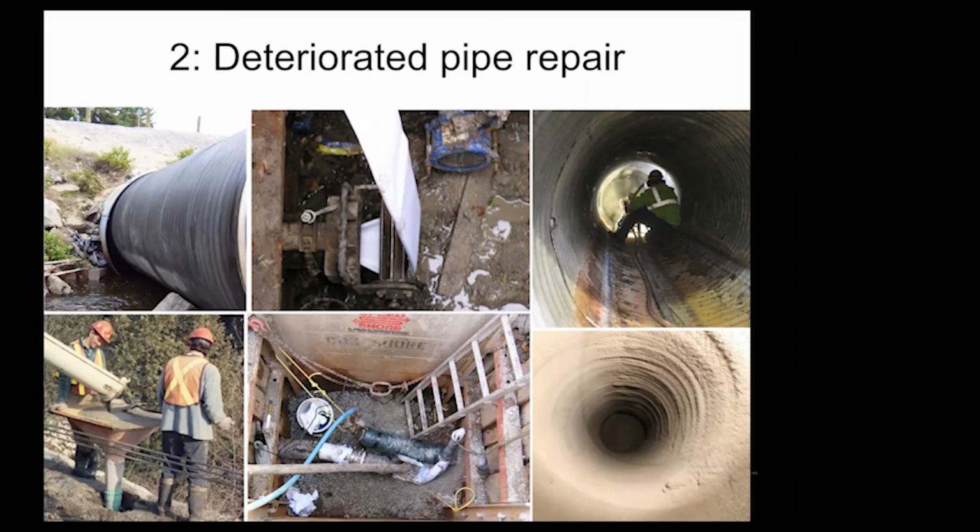and then once it slipped in place, there'd be grouting, and the picture on the bottom left actually shows the grouting of that structure using a simple standpipe that's drilled, so they just drill from the surface through the top of the corrugated steel. They've installed a simple vertical PVC pipe, and they're applying that grout just through that standpipe. The two photographs in the center show a pipe repair process using what's called a cured in place polymer liner.